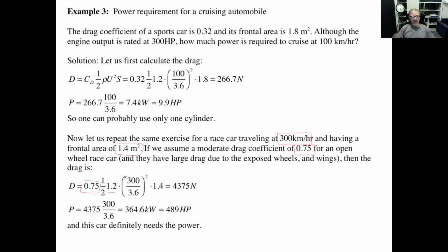And the density of the air, the speed is faster. Remember, the drag force goes up with the speed squared. Before we've been talking 55, 60 miles per hour. Now we're talking 160, 170. So we're doubling or tripling the speed. And we end up with 4.3 metric tons, roughly. That's a big thing. It's significantly more than the weight of the car.